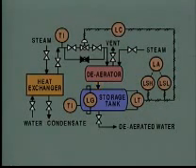The deaerated water storage tank has a temperature indicator, a level gauge, and a level transmitter. The level transmitter is connected to a level controller and to a level alarm system. The controller is connected to the deaerator level control valve that regulates the flow of water into the deaerator.